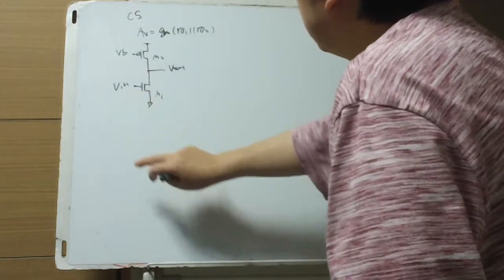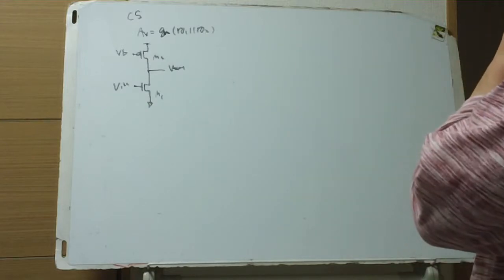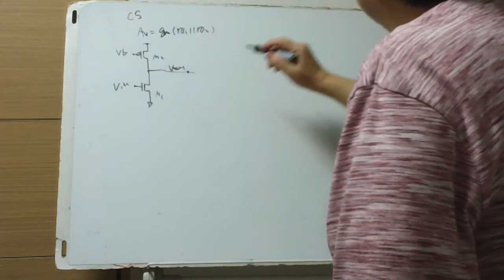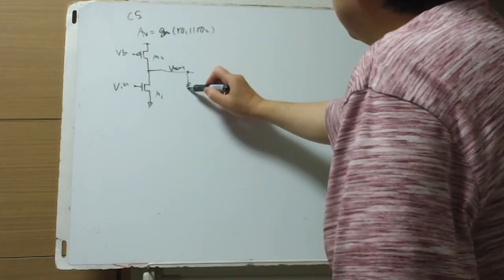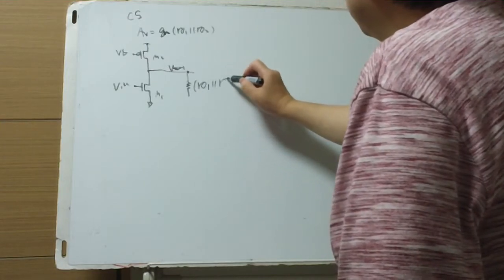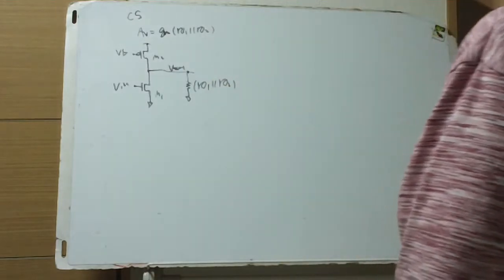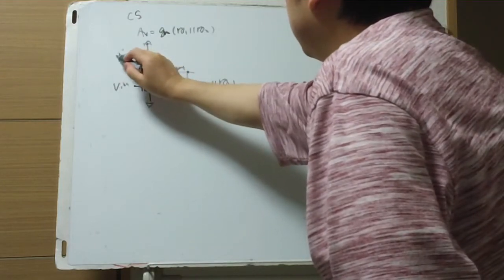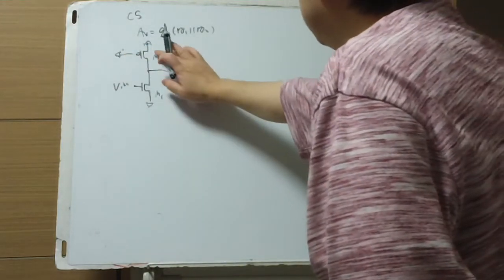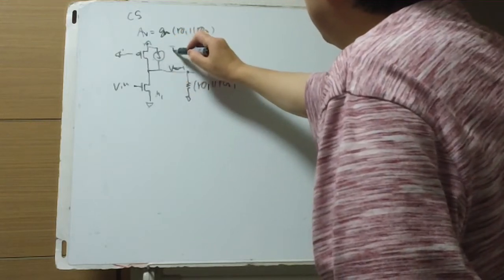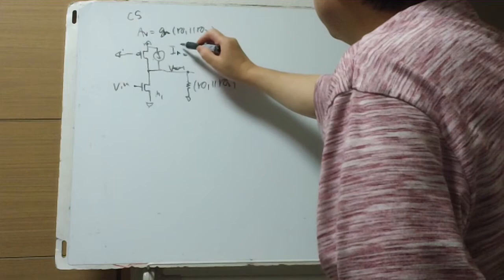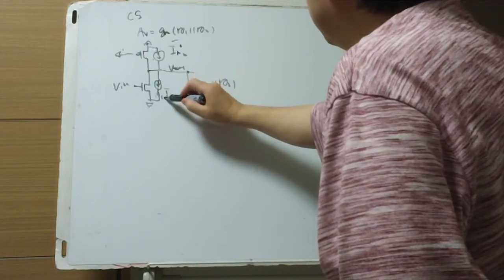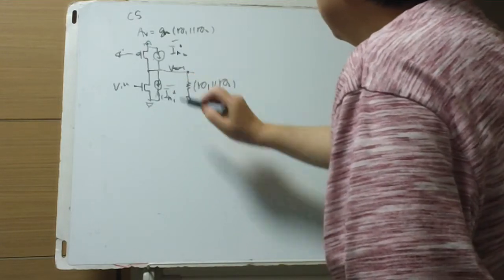And when we explicitly write R01 in parallel with the output resistance here, and this is ground, this is ground, and this is ground, expressly, this is In2 squared bar, and this is the current noise power In1 squared bar.